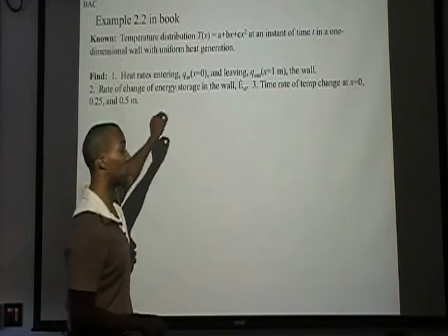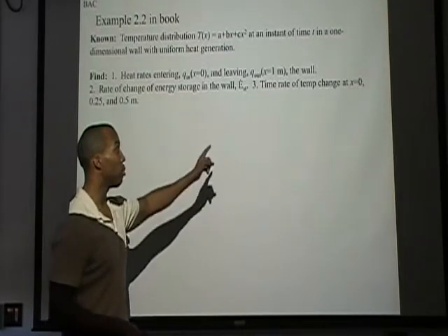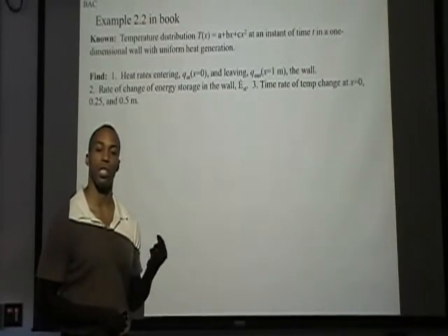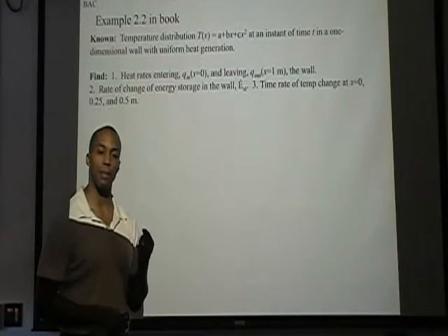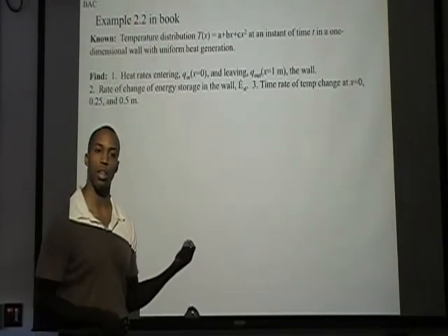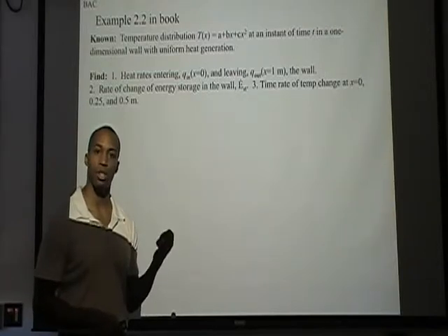Where it talked about energy in number 2, we can work with the general form of the energy balance. But when it talks about temperature, we need the heat equation to solve for temperatures. That's the difference. They're both energy balances. But the difference between the heat equation and the E in minus E out plus E gen equals E stored energy balance is that the heat equation allows us to determine temperature and how temperature changes with position and time.